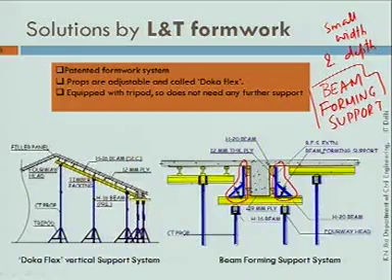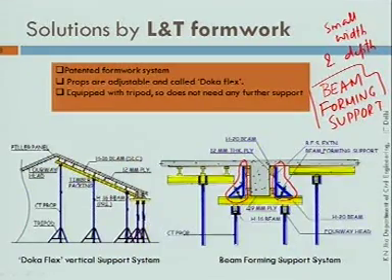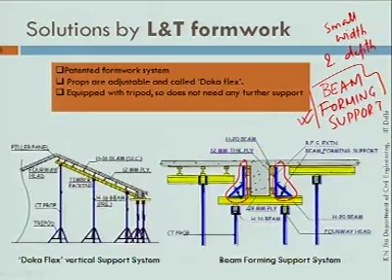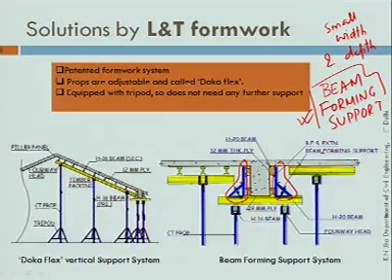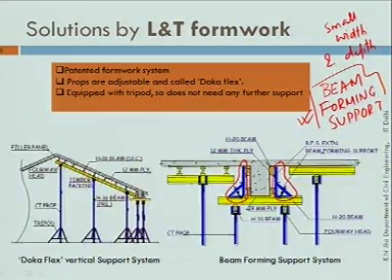So especially for a housing project, suppose you are constructing small buildings, the beam sizes are not great. So for such applications you can use this beam forming support. The advantage is you can see there is no use of timber. Timber is not required at all. So how it has been done is like this. You have H16 beam, rather this is H20 beam for forming the sides.